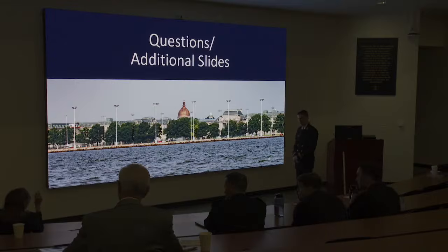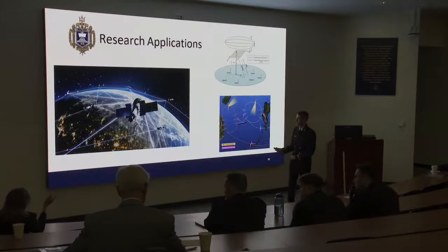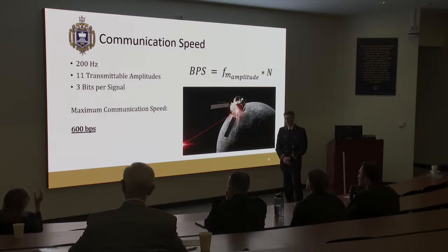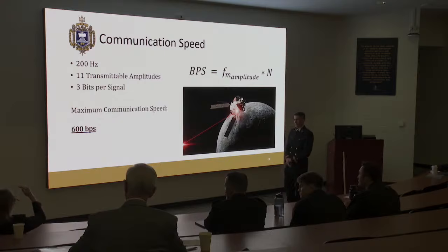Of course. So you talked about, in the end, you were going with a three-bit transmission. It only requires 8 levels. Yes, ma'am. So the fact that you were able to get 11 amplitude levels, are you building in some buffer there, or why not already reduce the amount of modulation to just get 8 levels?